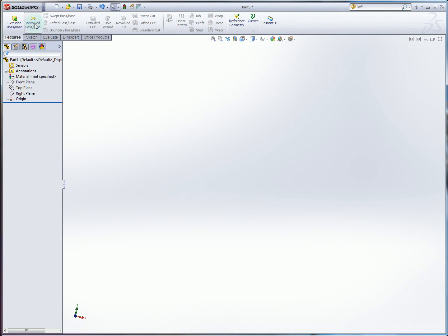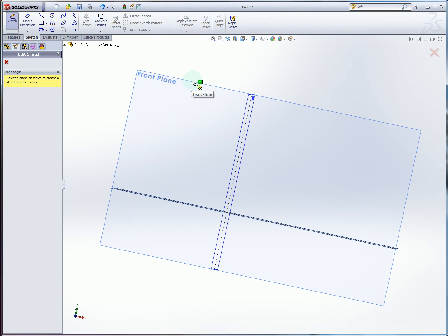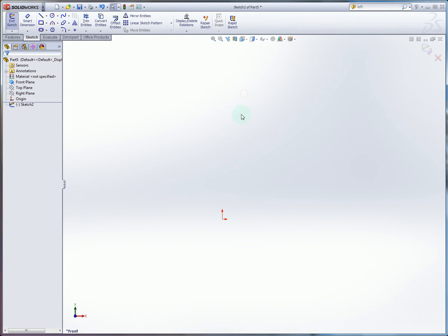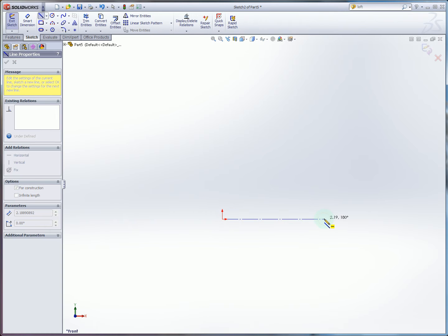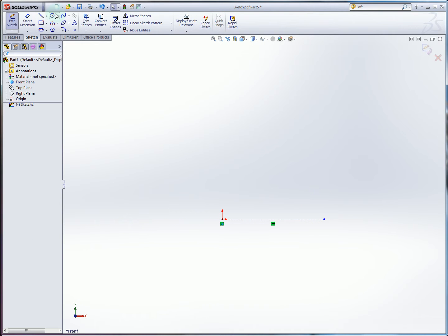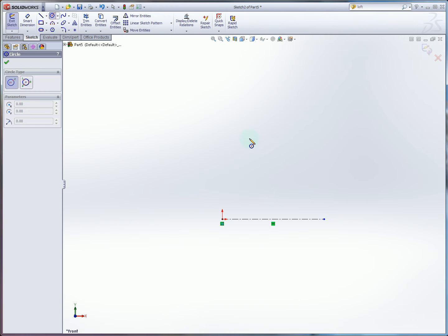I've rolled back the sketch, so now we're going to do the same thing with the revolved section. And we can do this either by clicking the revolved base or just create a new sketch in the direction we want. So for this example, I'm going to work on the front plane. And like with other revolved sections, we want to first draw a center line just so we have a reference to work against. And let's say I'm going to make a frisbee shape.